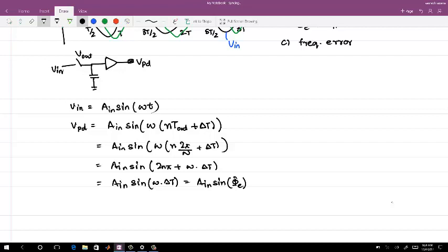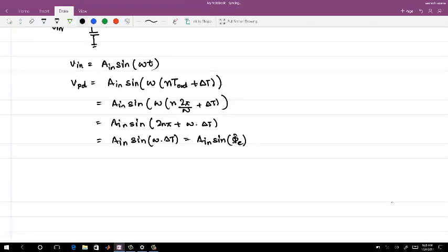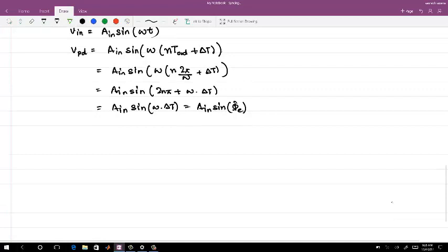Yeah, so what I would say is you consider that whenever the rising edge comes, you sample it. Means it is not tracking right now, or even if it is tracking, you are only considering the sampled value. Okay. So in terms of characteristics, the characteristics of this phase error detector are the same as the multiplier based phase error detector. I hope I do not need to draw the range and all those things here. So the range of this phase error detector will also be plus minus pi by 2. This is the monotonic range, right?